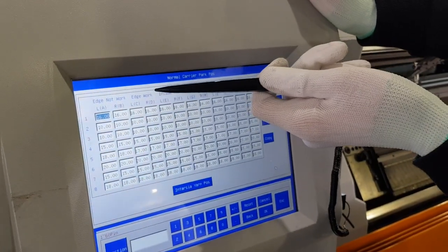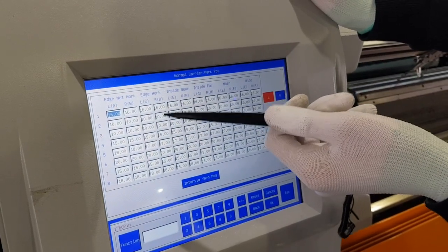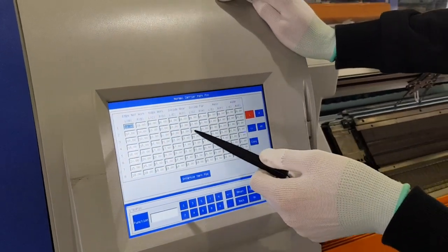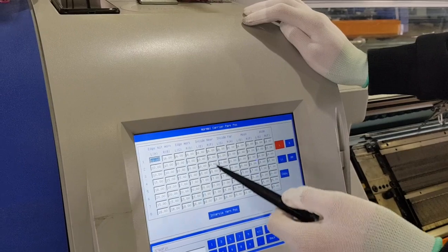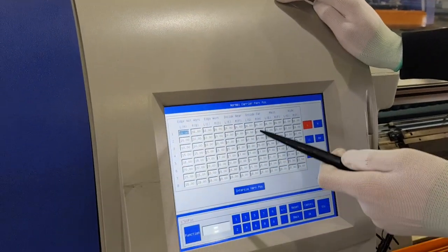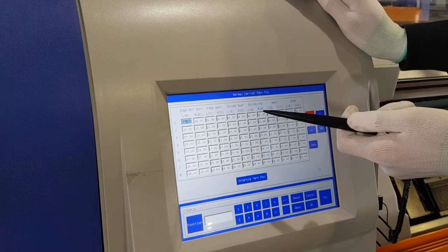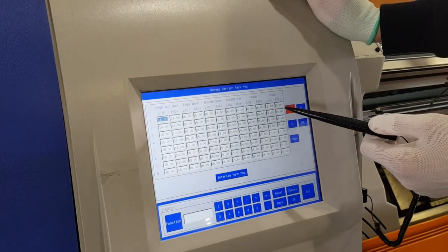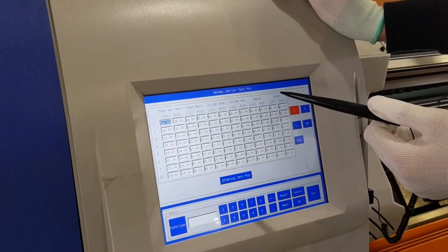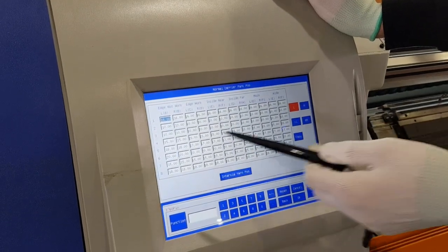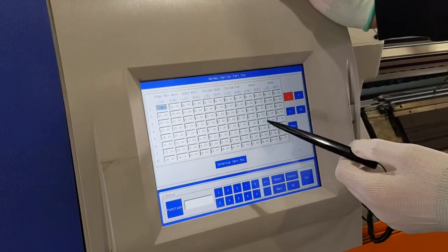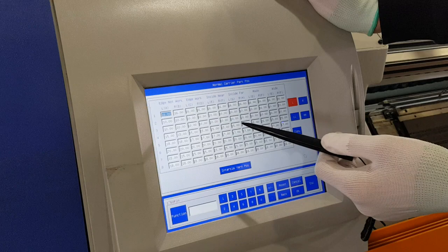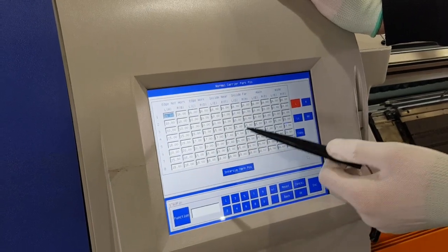The edge work refers to the yarn feeder, but next row will use the inside near and inside far. They are used for making part jacquard and intarsia. The inside far value is set according to the software. The main and wide refer to the pleating pattern. Normally, this value you can change according to the knitting situation, but here inside near and inside far, the value can't be set too small because the tuck can't knit.